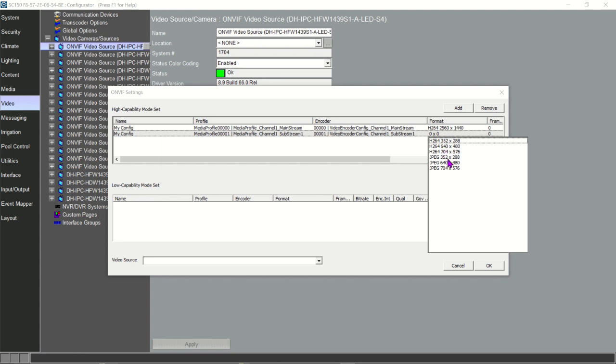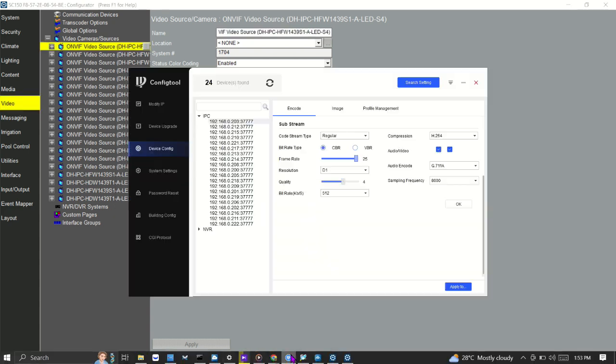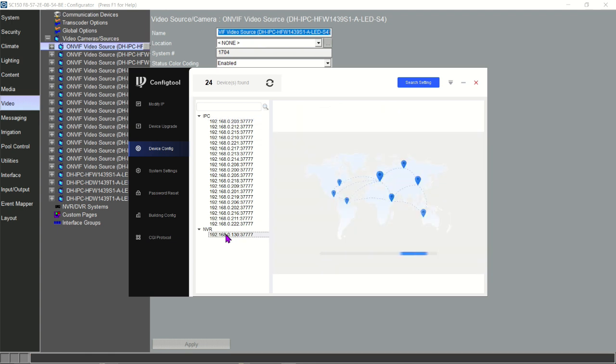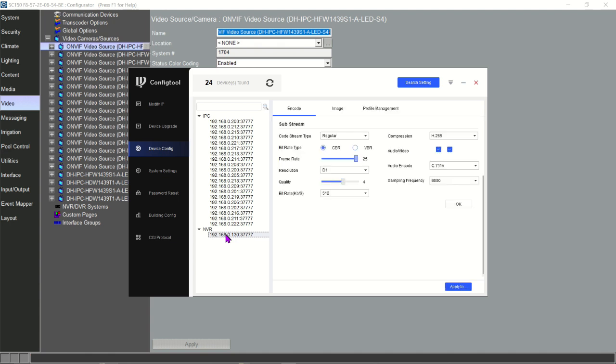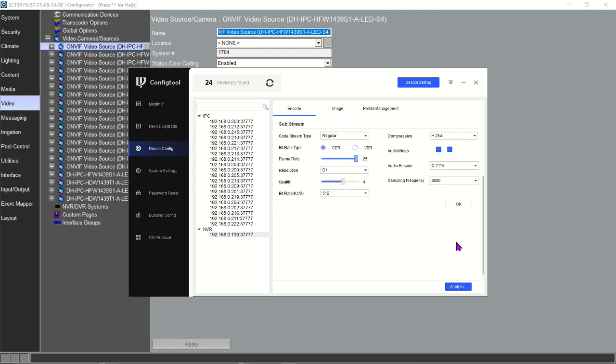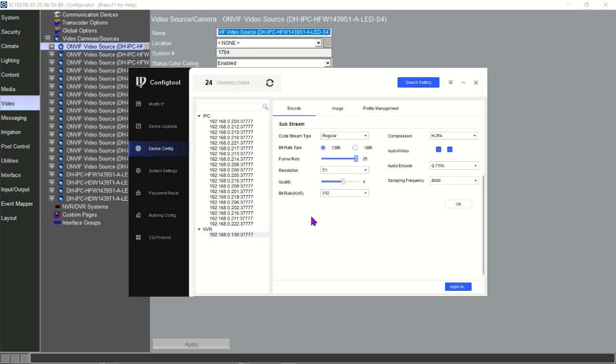Now, once we do this, I'll click apply. You would see those cameras pop up. Watch, we're going to the viewer. No, not here. Okay, I just want to change the compression here, because if I don't change the compression here, it's going to send those cameras back to 265. This is what I was talking about. So you have to prevent that. So you change it from the NVR, because the NVR has a controlling power on those cameras.